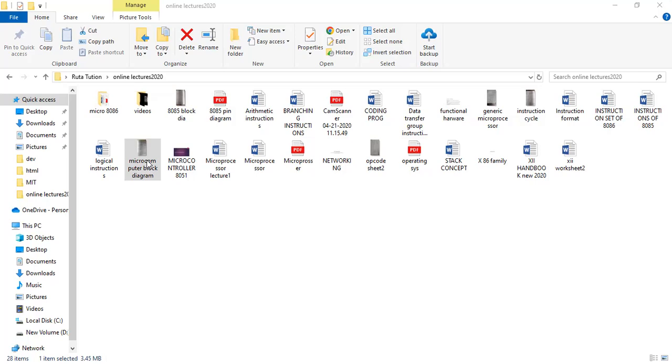See, if all the addresses are going to everyone and everyone tries to use that address, it will be chaos. Therefore, the address decoder is used, which will decode the address. For a particular combination of addresses, only one block will be selected. The address decoder will decode the addresses and send the chip select signal to either the display interface, keyboard interface, ROM, or RAM.